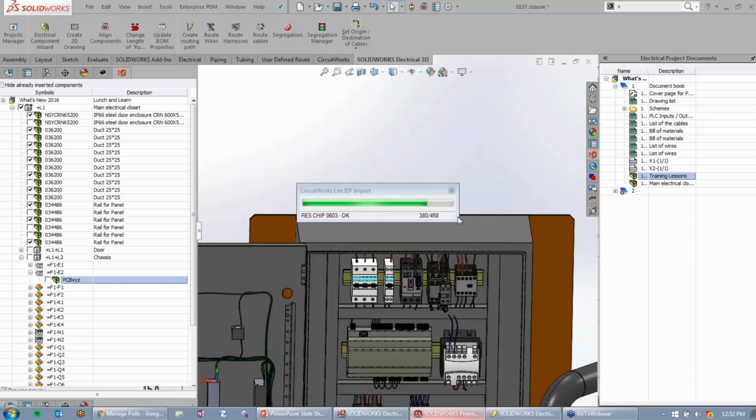See how close we are. Just about 50 more components. While this is going, feel free to ask any questions. Let me know what you like about 2016. All right, a couple more components here to get our 3D model. And once this 3D model is generated, it'll stay linked to that manufacturer part. So if a change does happen on the PCB, we can rerun this and it will update. But it does store the information once it's created as its 3D part.